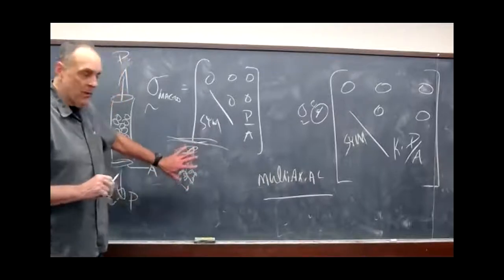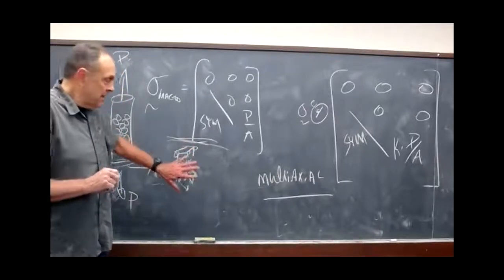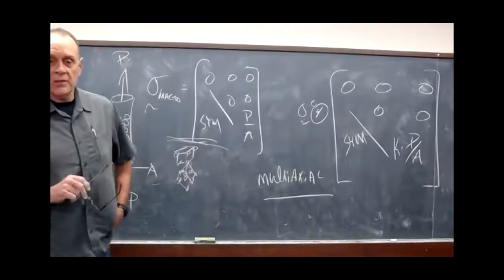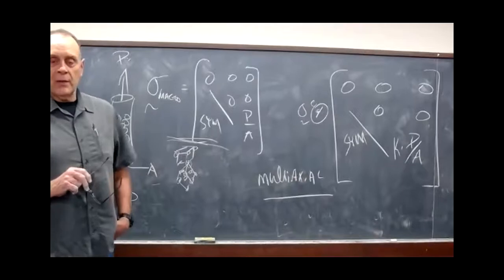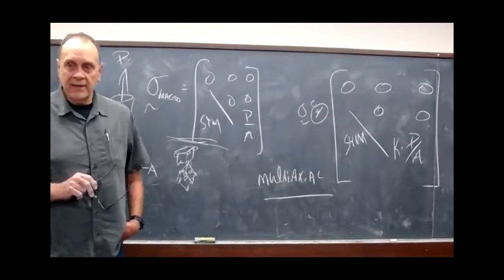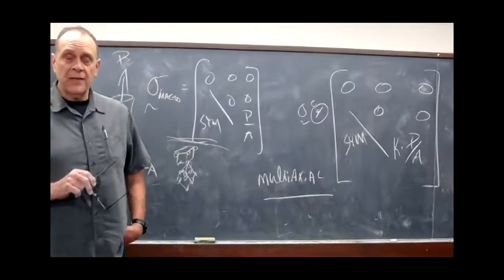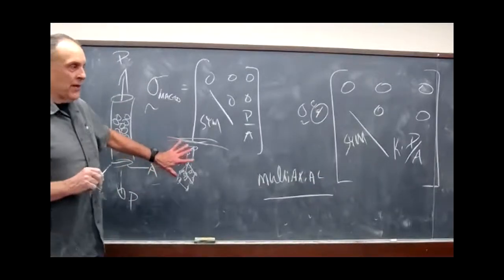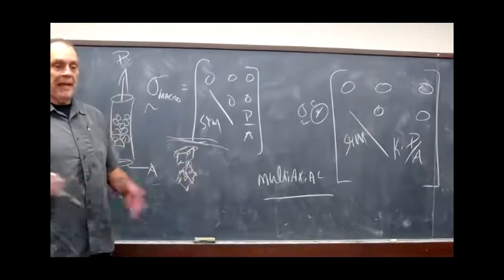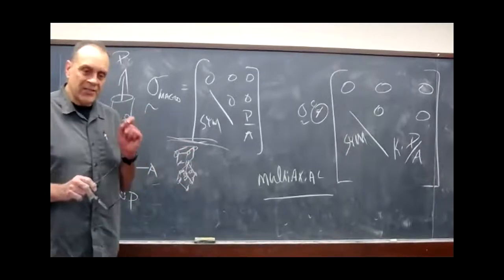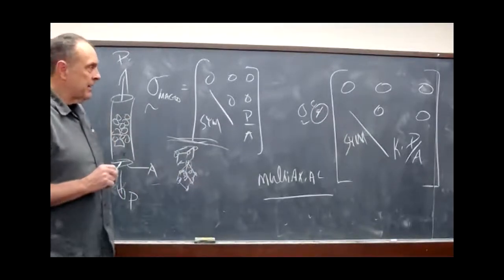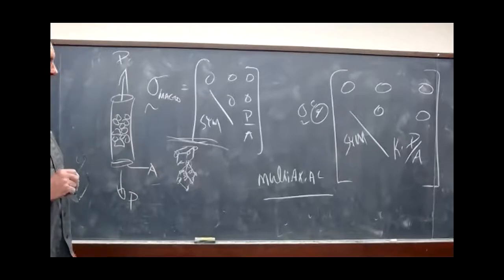But this is one of the biggest points that comes out of this: this is a rich and complicated stress situation on the crystal scale, and that's what opens up the doors to the things that you guys are working on. There are going to be some crystals that are good, some crystals that are bad, some crystals that are in a bad neighborhood, but they're not necessarily going to be loaded in uniaxial tension. So jerk that button off of your EBSD system, and we'll see you next week.